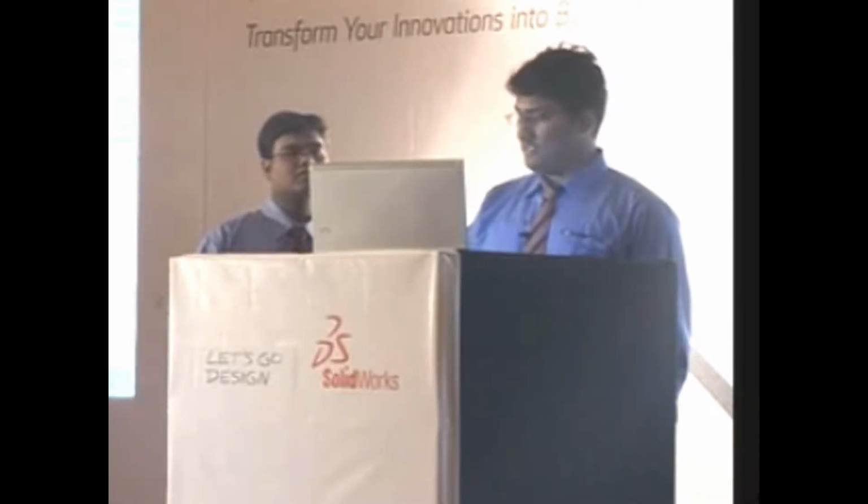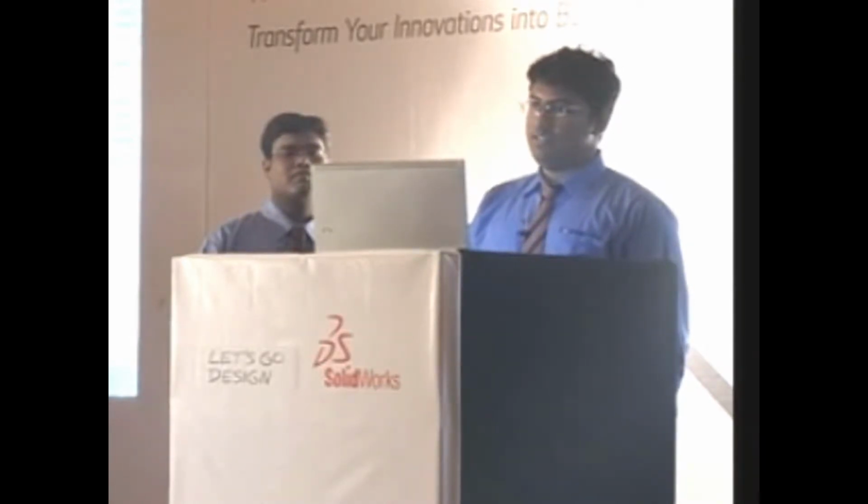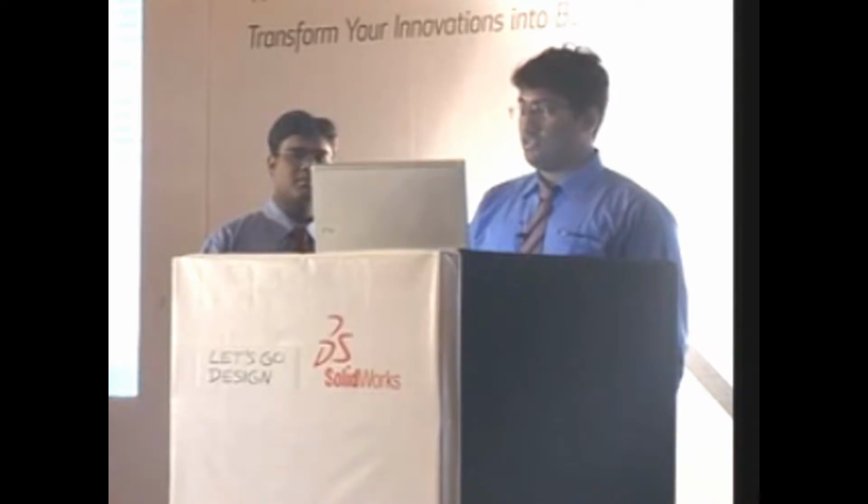Incorporate some limit value also for this dimension. Let me show you how exactly and how simply we can do that now. I'll just drop down this and say I want to have a dimension to be a limit. But just a single click on auto arrange automatically updates all the dimensions in the drawing on its own, having a proper spacing between them.